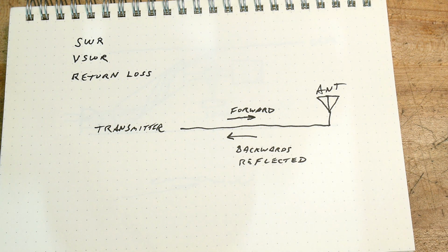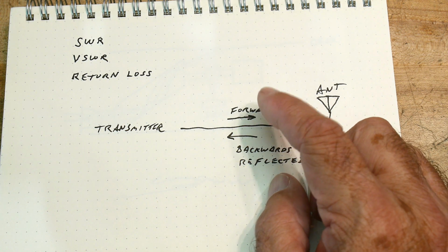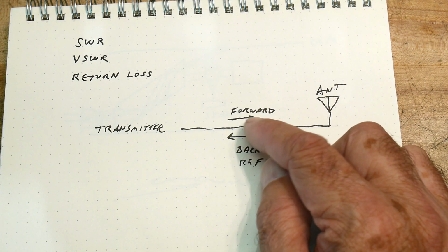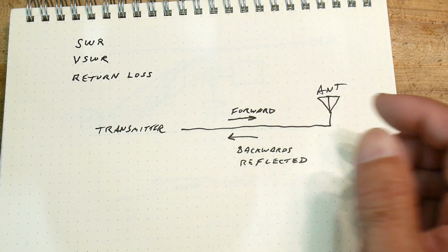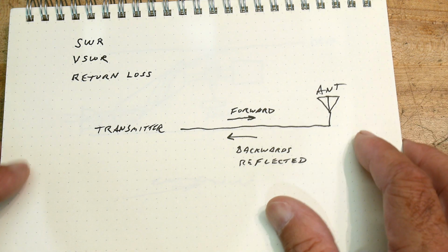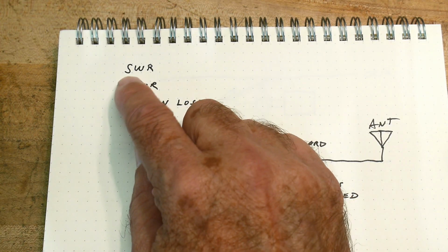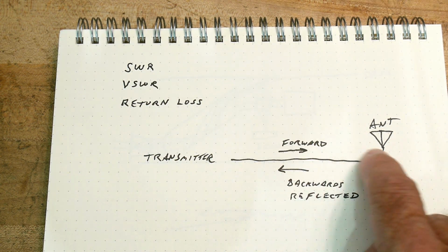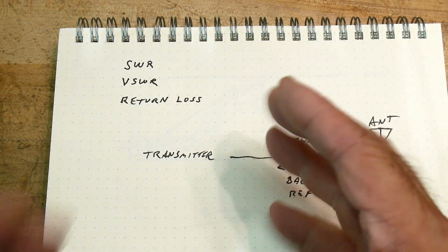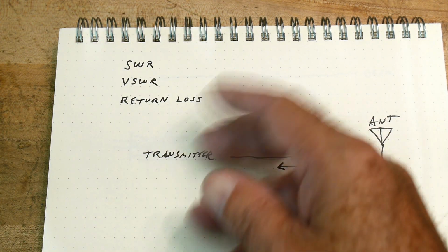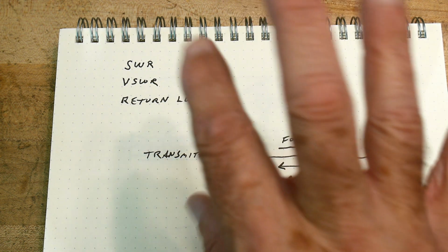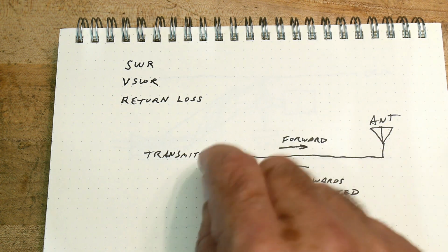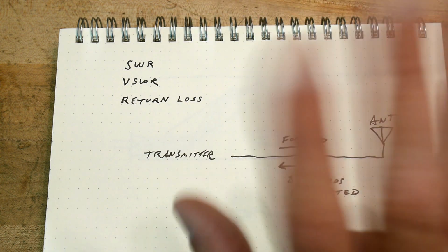And so anything that comes back is bad, and there's a ratio here of goodness to badness, and we'll talk about ratios and different units. You may hear the terms VSWR, which is voltage standing wave ratio. If you have a wave going this direction and then you have a wave going the opposite direction, they kind of interfere with one another and they set up a standing wave. And you can actually measure that in a physics class with sliding slots and stuff, and it's complicated.